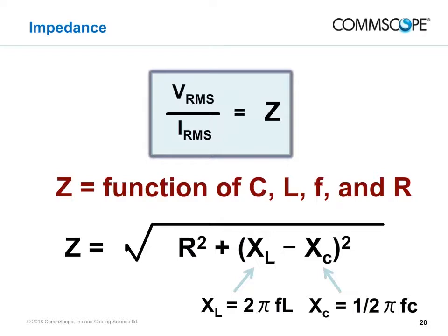over time. The formula for impedance is similar to the formula for DC resistance, but unlike DC resistance, impedance is not a constant. Rather, it varies based upon the frequency of the AC signal present at the circuit element and has capacitive, inductive, and resistive components.